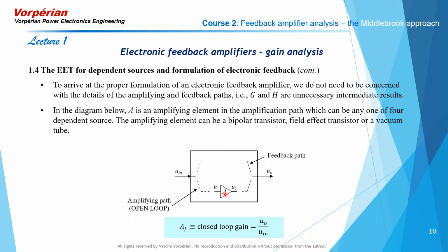And in that case, when it's infinite, your closed loop gain, the gain of this system, will be dictated by the feedback network, which is what you do in all your ideal op-amp circuits. So you're quite familiar with the idea that it would be a wonderful thing if this A was very, very large and ideally infinite. And let's see how we can exploit that to get to the feedback formula, the natural feedback formula, the one that's given by Dr. Middlebrook.